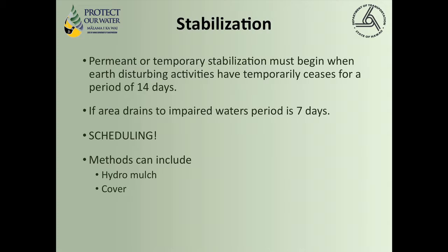Stabilization of any bare area needs to occur if the area is at final grade, or you're not going to work it for an extended period of time. That extended period of time by HAR 11-55 Appendix C, and this is also reiterated in your SWPCP, is 14 days. If you happen to be discharging to impaired waters, it's 7 days.